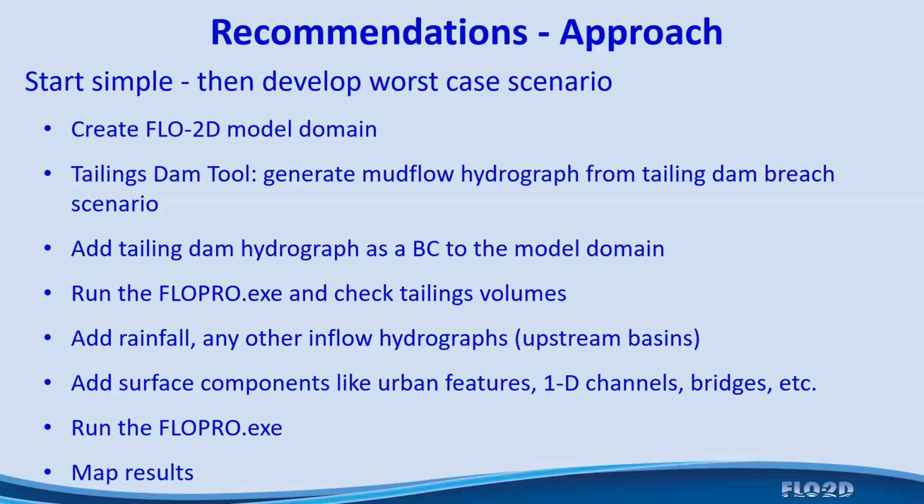And always check the volumes. Make sure that the volumes that you enter and select from the tailings dam tool are basically the same volume that is being distributed and routed downstream in your system, because again, if you are accurate with your volumes, the area of inundation and the mud flow extension will also be accurate.